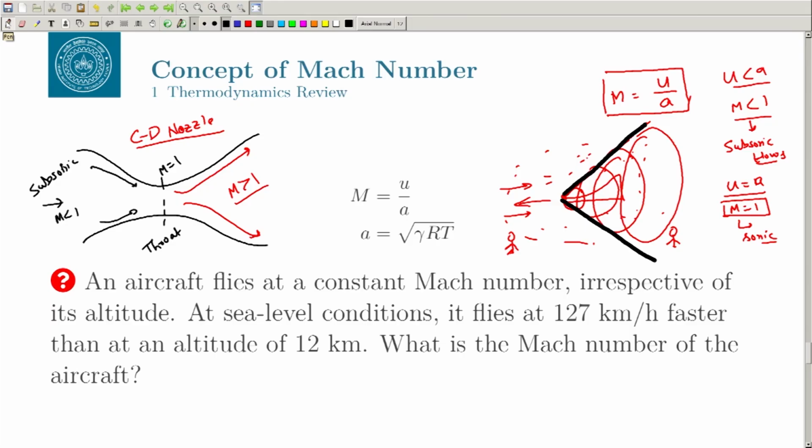We discussed the subsonic condition, supersonic condition, hypersonic condition, and even the transonic condition. Transonic condition is when the Mach number is between 0.8 and 1.2. In that case, despite the free stream Mach number being less than 1, you can get a shock on the body, because the flow will accelerate on the body and you might get a shock.